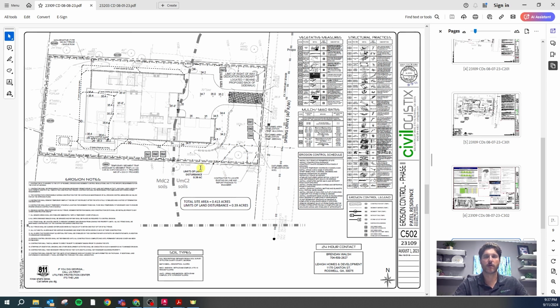If it's less than 1 acre, we can just do 1 phase. The first phase are the erosion control BMPs that you put in place before you start any construction. The final phase are the permanent BMPs that are left after construction is done. So the second phase, or the middle phase, is really the basic erosion control plan for the project.